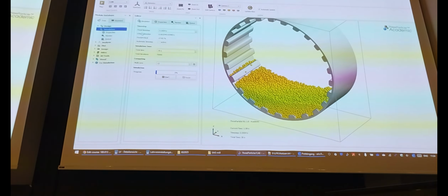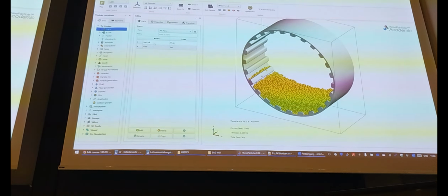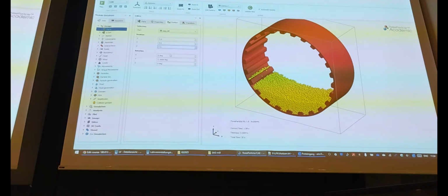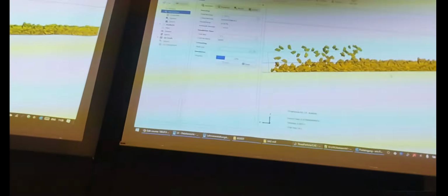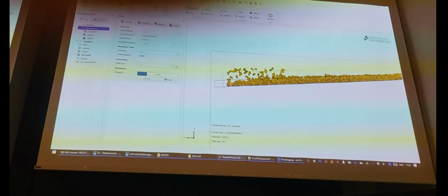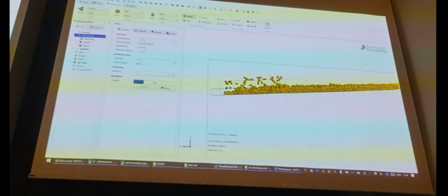And this is the second mistake that a lot of people make. They say, okay, I want to start earlier with the rotation or I want to change anything. They do not look at where they are working, because you're actually working at that time step. You can change anything here, right now, and resume the simulation. For example, I can change the segment in its angle. For example, change the segment here, so that it's nice. And then resume, and the material stream increases first, a little bit more particles than before. So you can change at any point. And that's important because lots of simulations do not allow that.